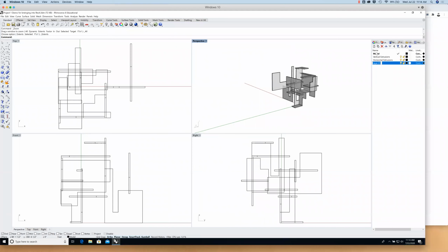I'm going to make a new layer. I'm going to call this glass or glazing. Glazing and glass usually all refer in architecture to windows and curtain walls, basically looking at glass. I'm also going to make sure that this new layer, glass, is checkmarked. I'm going to click where that checkmark column is. That's going to make this the active layer. So now when we start to make new objects, like surfaces, they're going to be on this glass layer automatically. I don't have to select them afterwards and change their properties again.